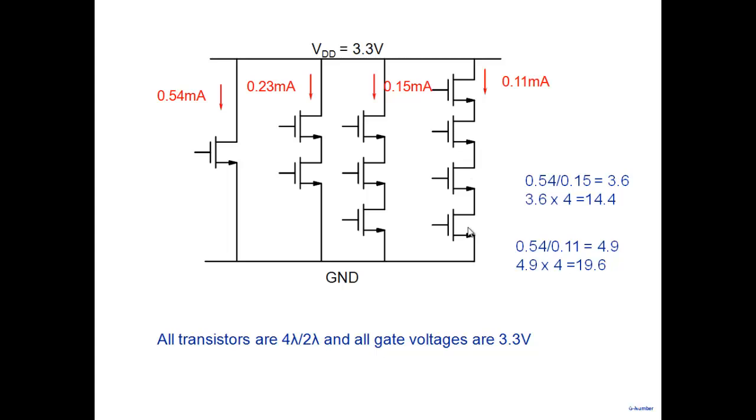So this is getting into a problem. The transistor sizes are becoming large, their capacitances would become large, and so you're saying 20. If I had 5 of them in series, the current would have fallen even further. You may have required, I don't know, maybe 30. So very rarely would you find anybody making more than a 4-input NAND gate. You're seeing why this is happening.